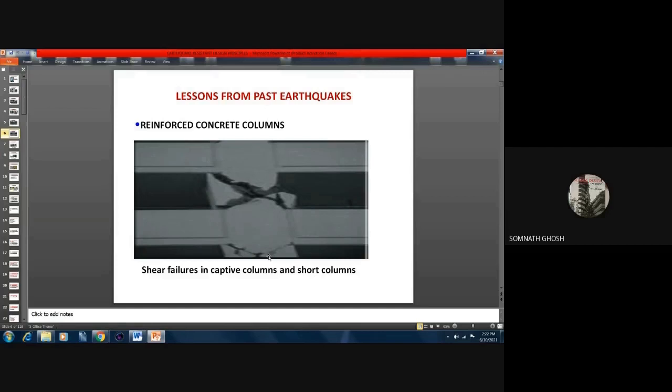And when they are doing like this, then the column stiffness increases. It will attract more force. There will be a huge moment. And if the column is not reinforced accordingly, because this extra beam is given just before that, so whatever the column reinforcement available, if it is not sufficient, then there is a possibility of shear failure or any other kind of failure like this.